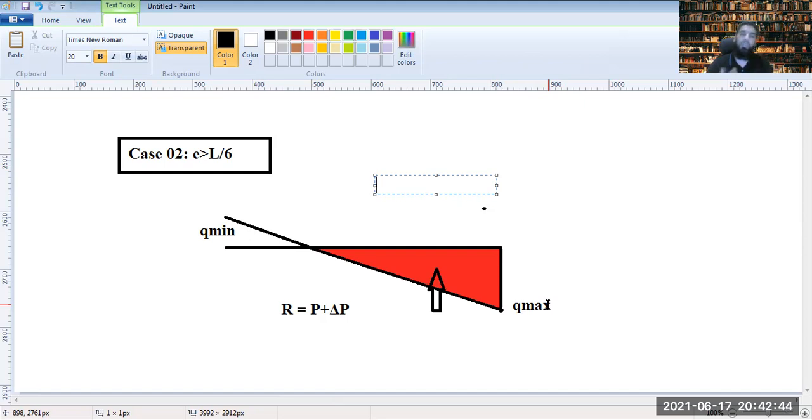We cannot eliminate eccentricity as a whole, but a large amount of eccentricity would lead to greater moments, and greater moments then lead to soil failures. So our focus should be that we avoid the soil failures by distributing all the load from the footing onto the soil.